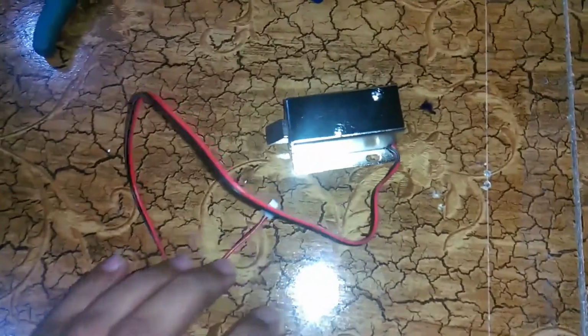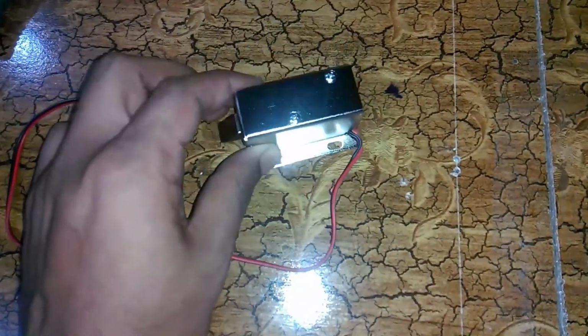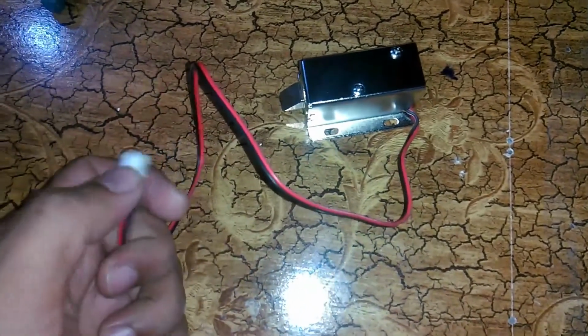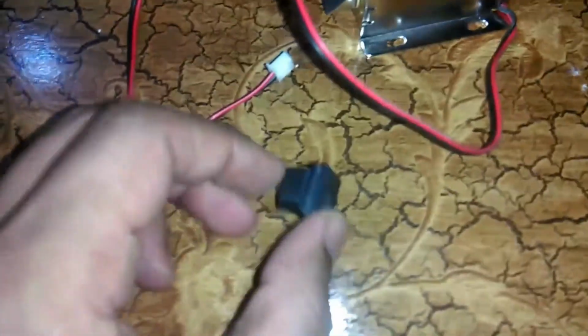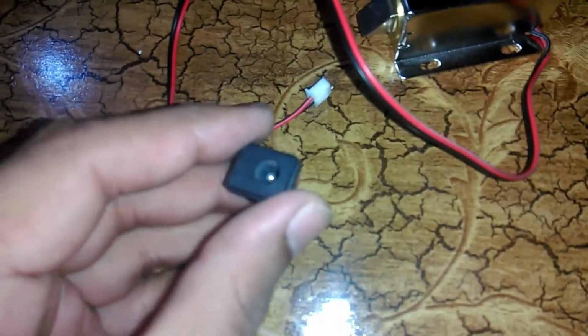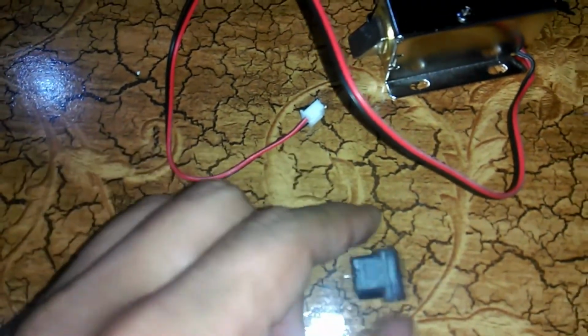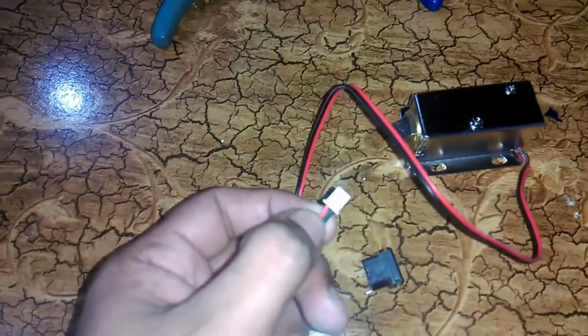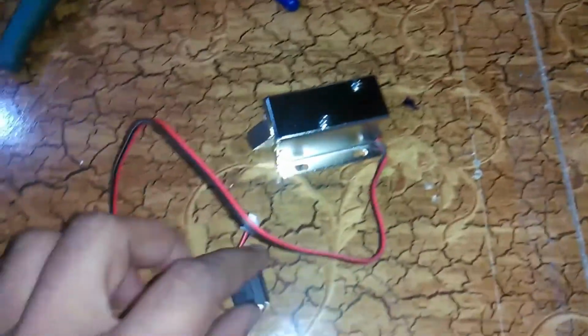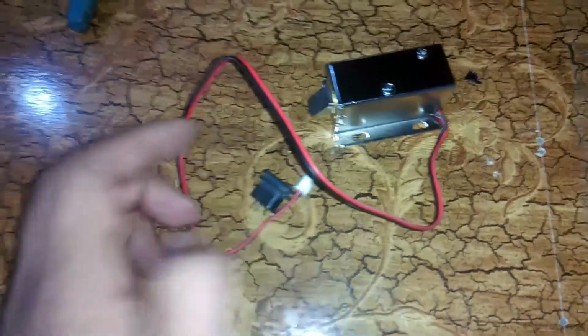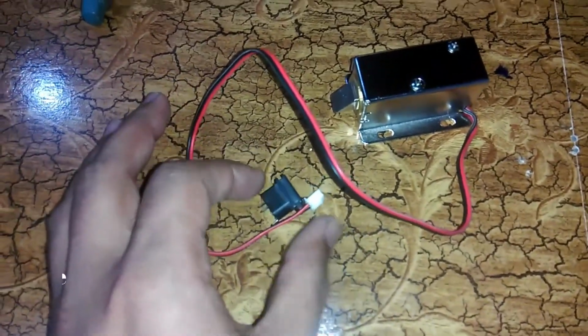So this is the electronic lock that I will be using today. Actually I don't need this, so I will cut this and connect a DC socket so that I can easily power this up using a 12-volt adapter. I'll cut this and solder these wires, and for this I will need a cutter and a wire stripper. The wire stripper is optional if you can remove the insulation with the cutter. Once I am done with the soldering, I will be back and then we will start soldering the relay driver circuit.